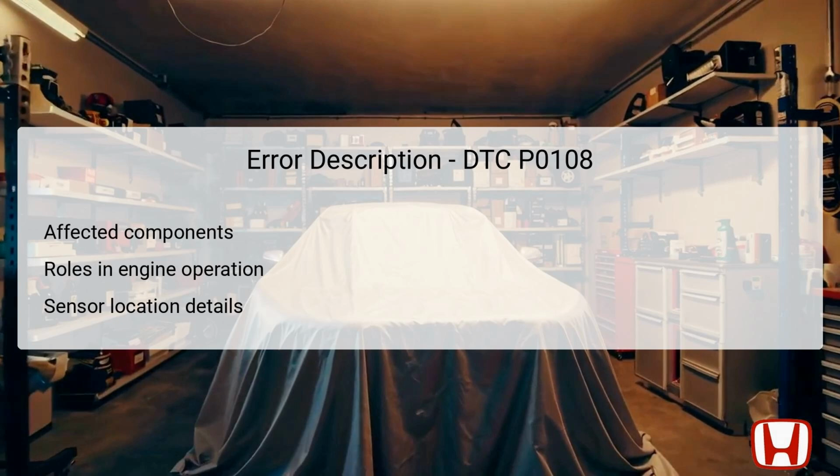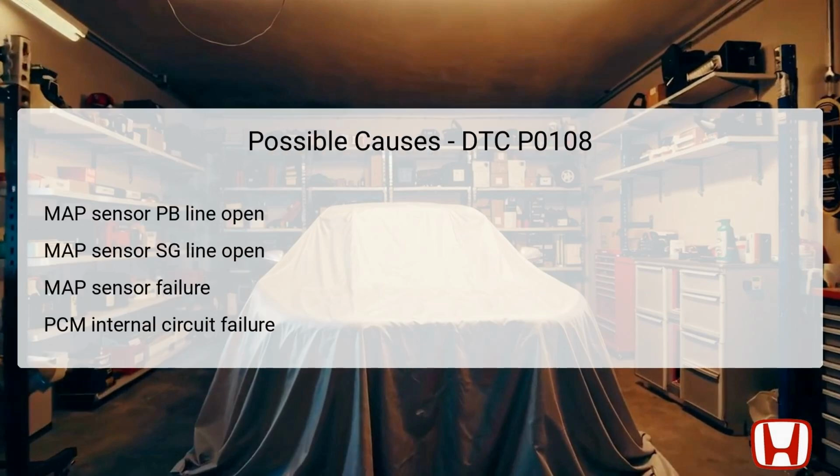Notably, erroneous signals from the MAP sensor can lead to poor engine performance, increased emissions, or even damage over time. Generally located near the intake manifold, the MAP sensor must be intact and properly connected to function correctly, ensuring accurate readings that the PCM relies upon. Several possible causes can lead to the activation of DTC P0108.